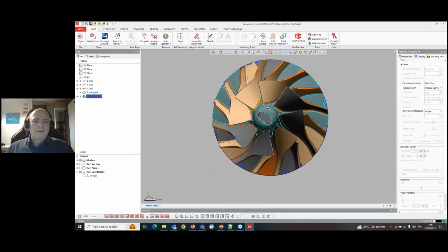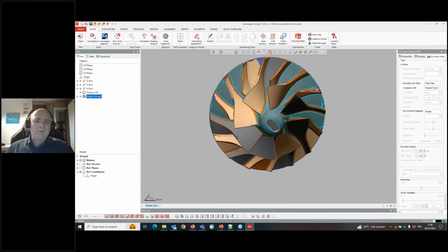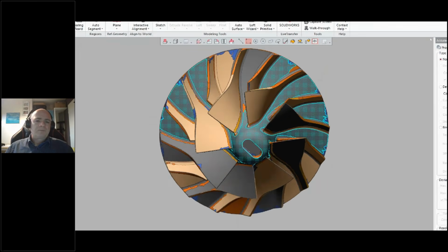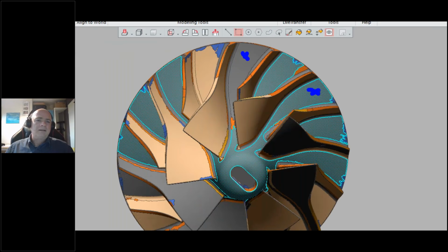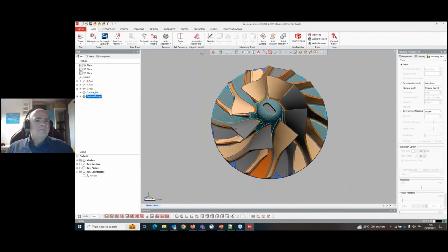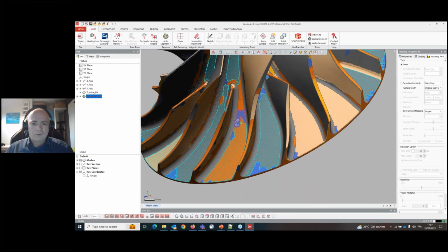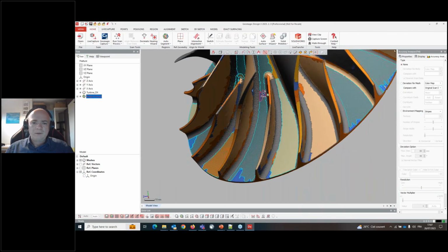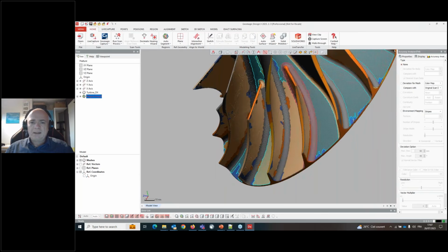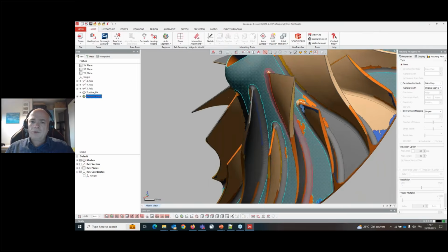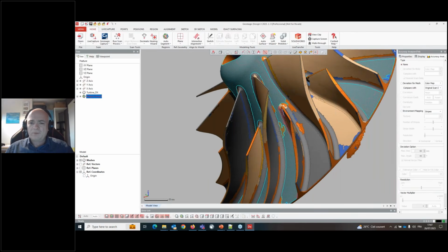But the issue here is that you can see that this region includes those areas here, but it didn't take that one or that one or that one and all around. So I would prefer to have all those regions at once. So I will just need to select those regions along with the main one. I will add the selection to those regions with the Shift key to add. And then at the end, I will tell the software to merge everything I've selected as one region.